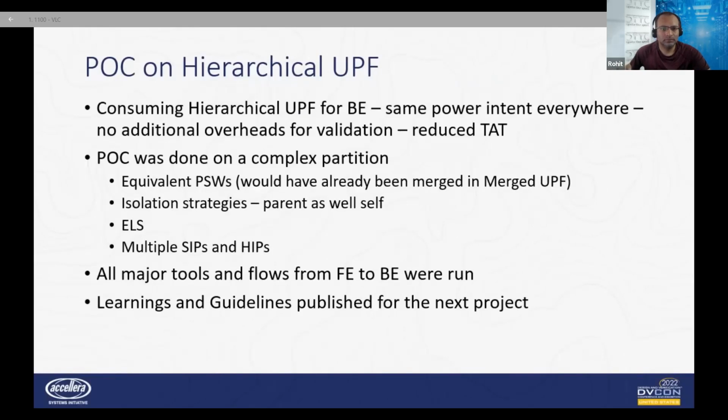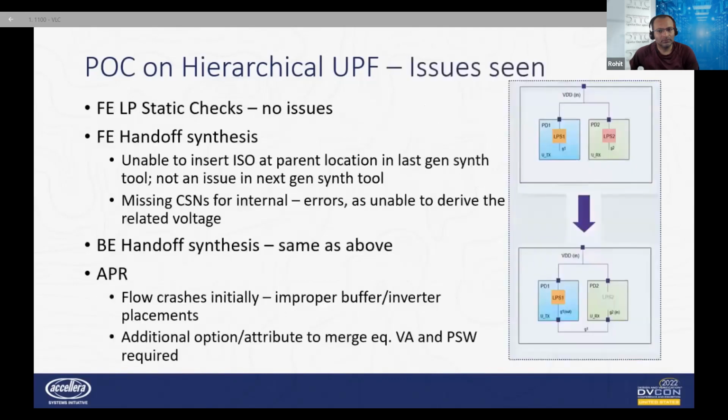This partition actually contained equivalent power switches, isolation strategies of both parent and self location, enable level shifter strategies, and multiple soft IPs and hard IPs. In this POC, we ran all the tools and flows in front end as well as in back end. And then we published the guidelines and learnings for the next project so that they can easily do the necessary change and consume the hierarchical UPF. Now let's see all the issues seen during our POC on the hierarchical UPF.